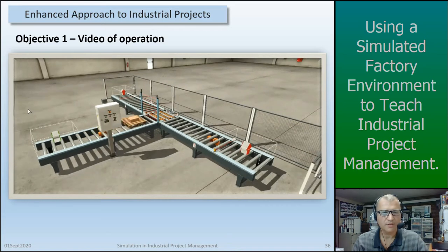Go through the height detection system onto the diverter. It's detected that it's a low box and it shifts it off to the left. As soon as it hits the remover, it dissolves and disappears, and a new box appears at the emitter. Notice I'm only doing one box and pallet at a time. Now I've detected a high box and it moves it off to the right.